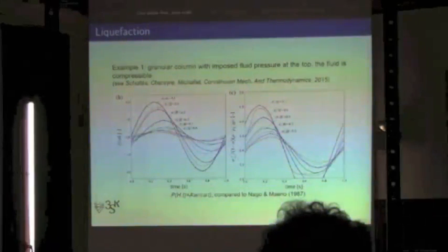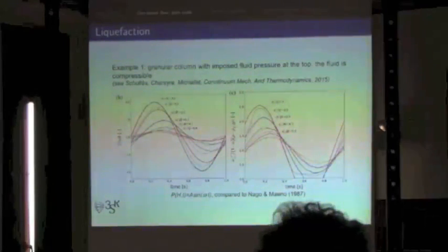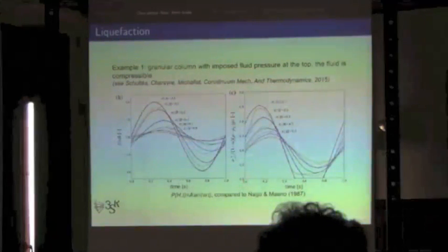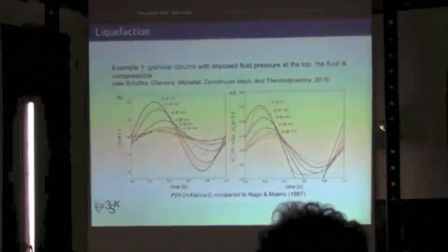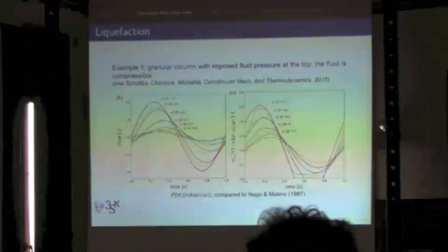And if you know granular materials, you say this is nonsense. You cannot have traction in a granular material. In the paper where they reported the analytical solution, they were smart enough to start the plot of effective stress versus time at 0. So they hide that part where the effective stress is actually negative, traction. But still they use a solution where it happens. They just don't plot it.